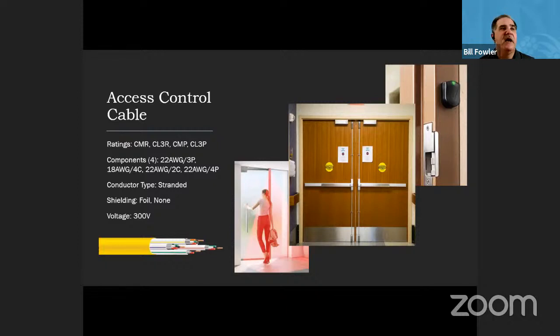So when we look at this system here, there's a good picture there at the bottom. The term is called Siamese cable. Basically, we've taken like 2 or 3 cable types and put them into one single jacket. We see this commonly done in this way because it saves on the support structure needed to take that cable from the security or access control point to the door location.